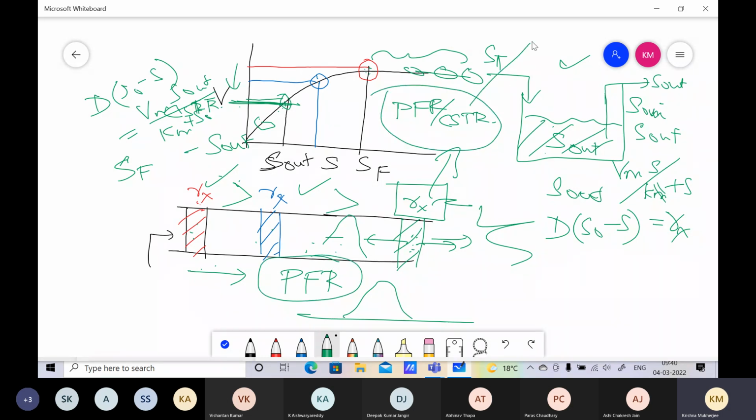And let me ask you this very simple question. This now you can at least answer. As Km increases, does this ratio, PFR by CSTR, increase or does it go to 1, if you take higher values of Km? Come on, let us have these answers. As I have written it down, as Km increases, what happens to the output efficiency of PFR by CSTR?